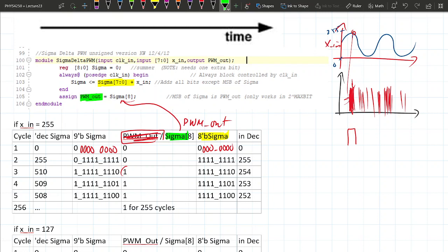We're going to do this a couple more times. Sorry if you're falling asleep. Well, next cycle goes around, Xn is still 255, it's just stuck there. 255 plus 254, instead of 510, it's 509. The binary version of that is the same thing, but then the zero is just shifted over one. You start to see maybe like shift register work here. It's the same idea, actually. You're just shifting this zero over and over again.